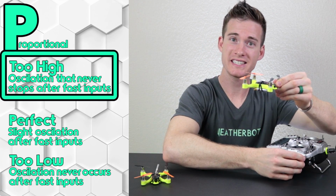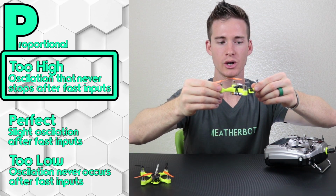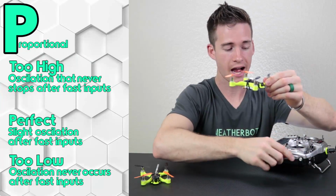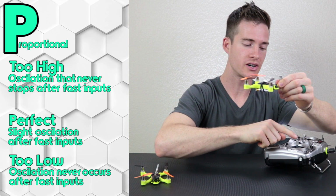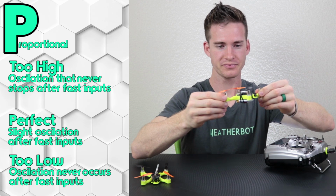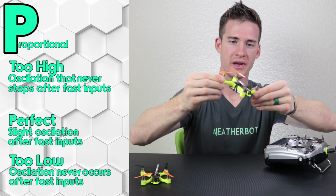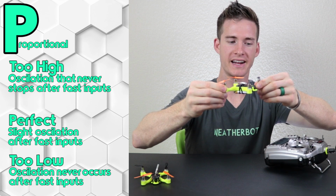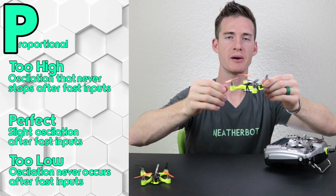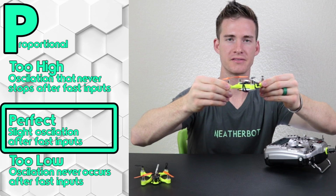At that point, you want to stop increasing P and start decreasing P, continually trying to hover, and that vibration will eventually go away. Once it's gone, stop decreasing P, and start giving some really sharp inputs in the pitch and in the roll. What you'll notice is when it pitches, it's going to vibrate and come back, and you want it to be able to dampen eventually. After a couple vibrations, you want it to settle out.